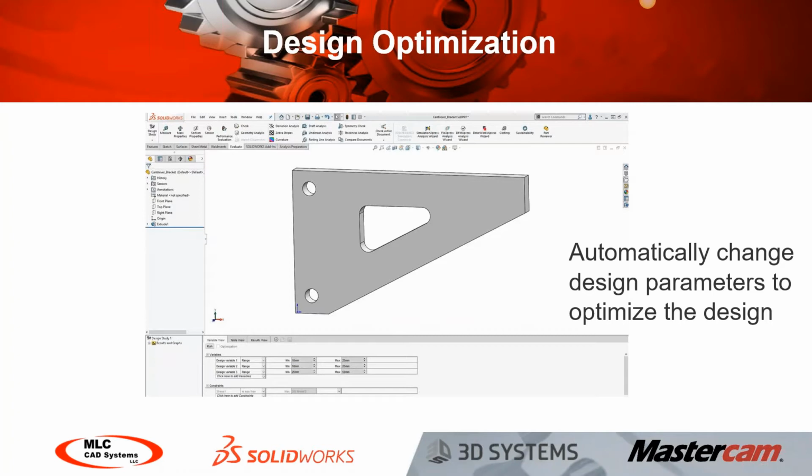So we have to specify which dimensions we want to change and what range we want those dimensions to be changed within. So we have to have some forethought in what the final design should look like beforehand. And the output we get in the design study remains parametric. It's only changing those parameters that we told it to change. And so there is some limit as to just how optimized our design can get.